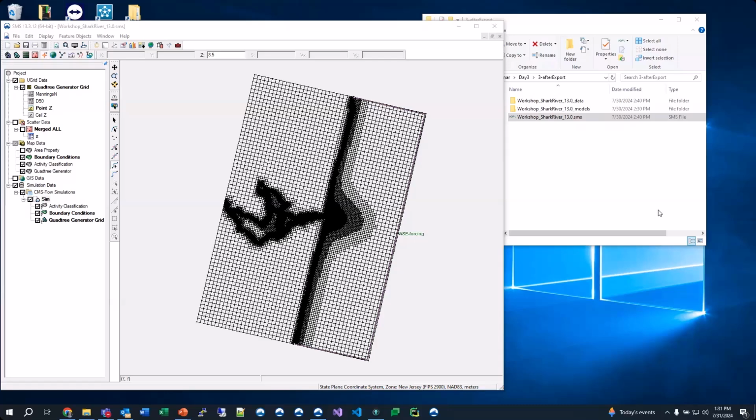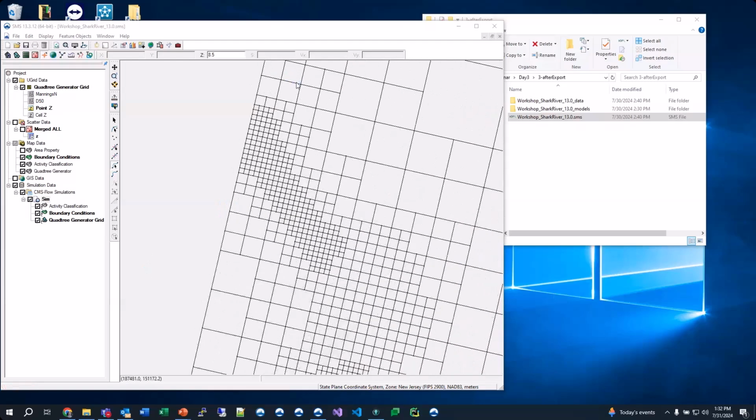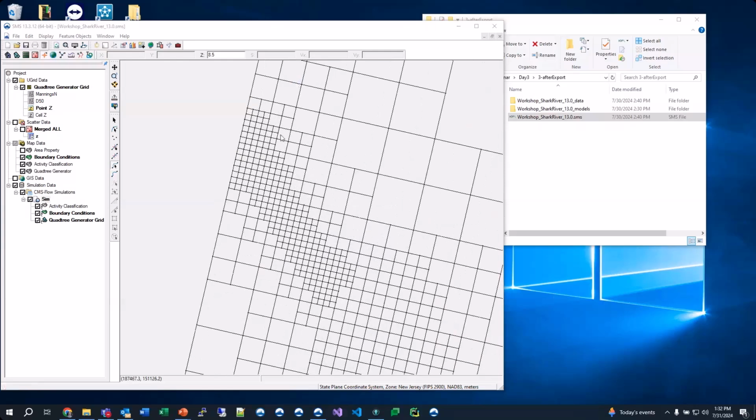Okay, Bruce, do you have a question? Yeah, when you were talking about the flow forcing for the river boundary condition, your flow coming in perpendicular to the grid was not in the direction of the basic river channel. Would you put the flow in perpendicular to the grid and let the model sort itself out, or would you use that direction correction to try to get it started in the right direction?